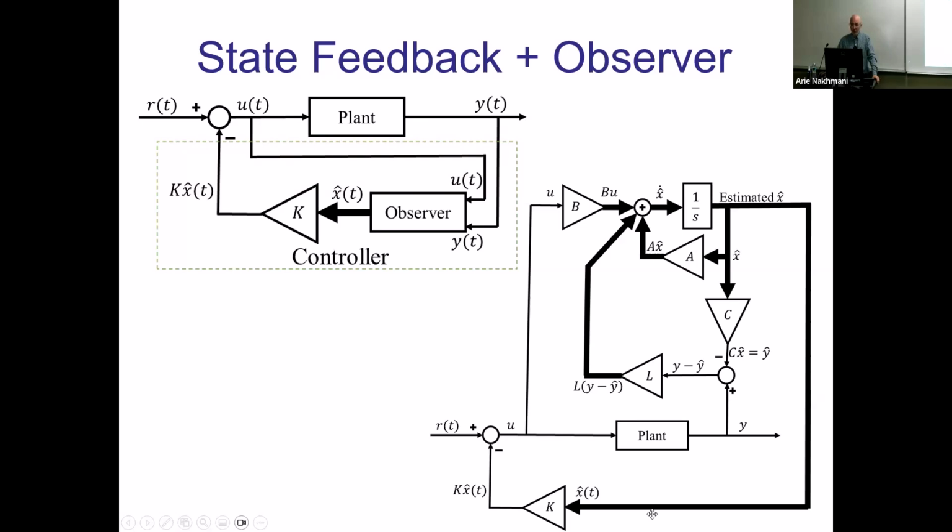And what I'm going to show you is that after I connect this horrible, big, complex system, your transfer function from here to there will not change at all. All of that will magically disappear when you're computing the R to Y transfer function. So all of that will not have any effect on the actual plant.